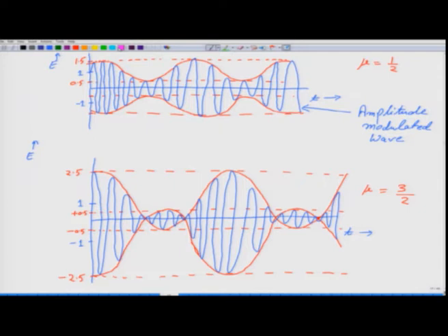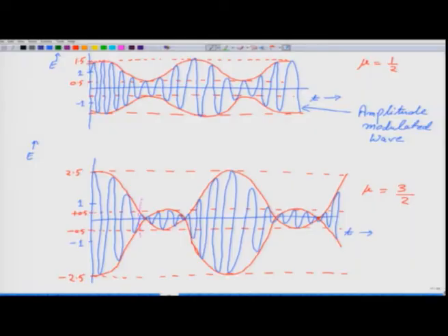Now if you pay close attention, the shape of the amplitude modulated wave is now very different from the shape of our original message signal, the modulating wave. The shape has changed quite a lot. Let us have a look on the graph. So this section is unwanted. Similarly, this section is unwanted, because at the receiver end, although this signal was not present in the original message, it has now appeared in the amplitude modulated wave, and this will distort our signal.